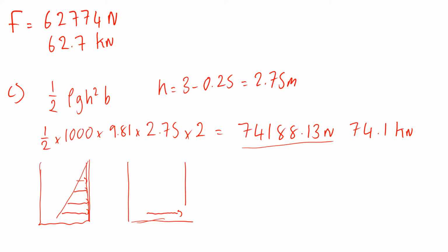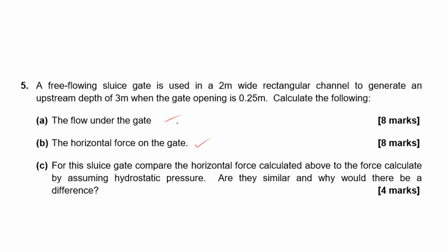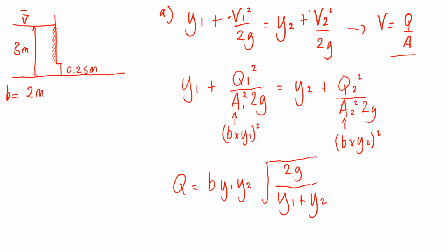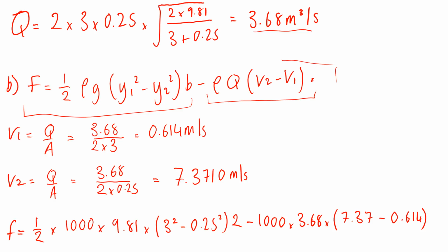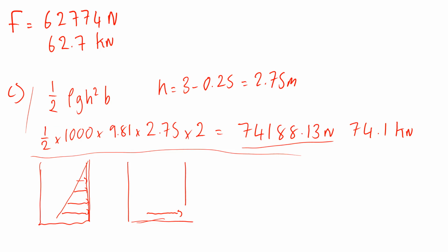So that is the solution to that question. That would gain you the full 4 marks. To do all that and then explain the difference, which is mainly because it's hydrostatic, the fluid is at rest, the force will be greater compared to when the fluid is not at rest, because the momentum is subtracted out of the flow.